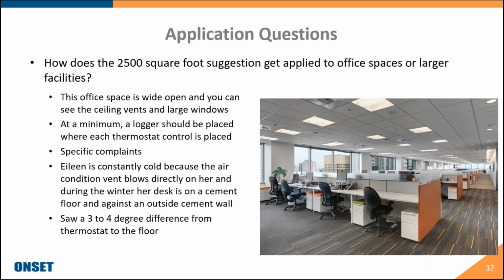One example I always like to talk about is one of my colleagues, Eileen, was always constantly complaining that she was cold because the air conditioned vents were blowing directly on her. And during the winter, her desk is on a cement floor and against an outside cement wall. So we actually did place a data logger by her desk and one by where our thermostat is. And we actually did see a 3 to 4 degree difference from the thermostat to the floor. So we were able to confirm that there is definitely a temperature difference from what the thermostat was reading versus where she was sitting in our office.